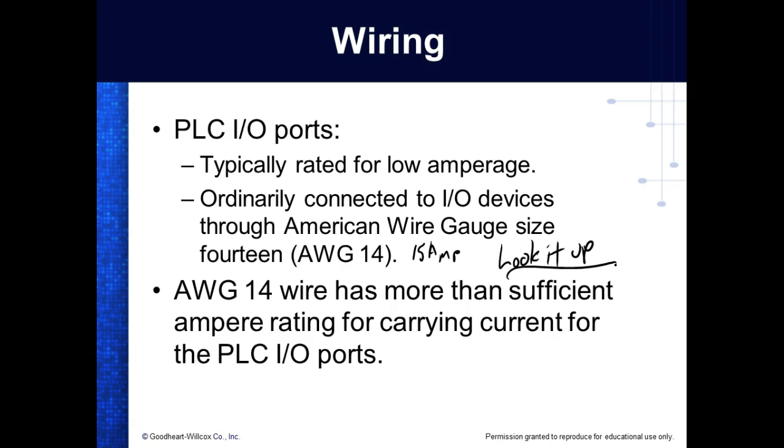I don't think I've ever seen one using 14 gauge wire. Pretty big. Yeah, it is. That's the main wiring on your house. We use either 14 gauge or 12 gauge. NEC rates 14 gauge at 15 amps, and they rate 12 gauge at 20 amps. And that would be for your base plugs. After that, when we get out to air conditioning and stuff like that, the wire size has to go up.